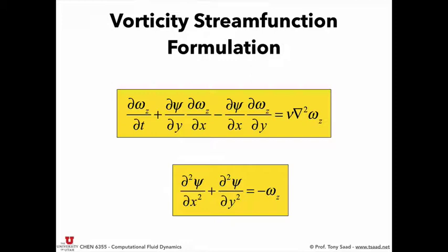So now, going back to the homework, given an initial condition for the vorticity, and typically vorticity is something that is generated at boundaries. Why we focus on boundaries initially, how you inject vorticity into domains, because at a boundary, the flow goes to 0. So let me help fix the ideas in your mind just a little bit. Let's take a flat plate, okay? And there is uniform flow going here. So put a fan, let it blow air in the middle of the room away from everything, and just put a flat plate in between.